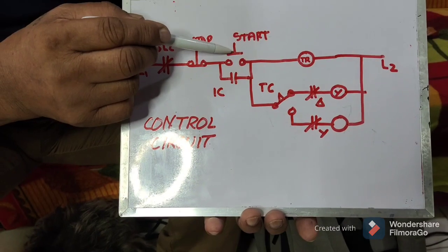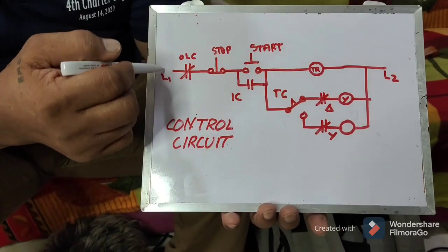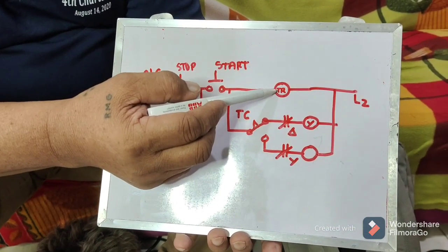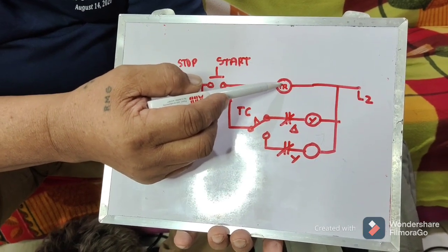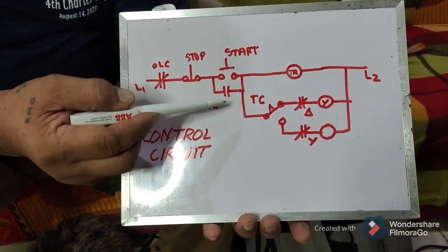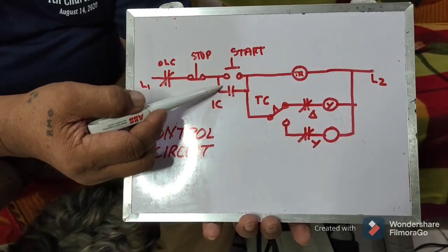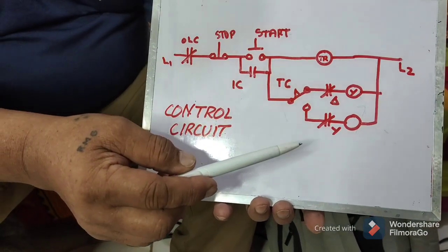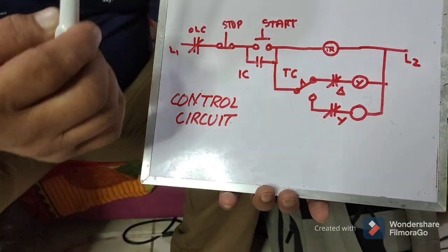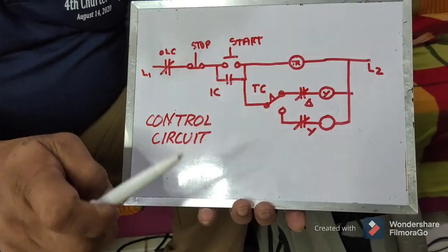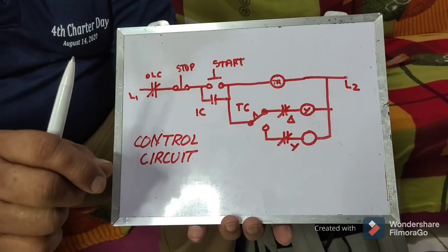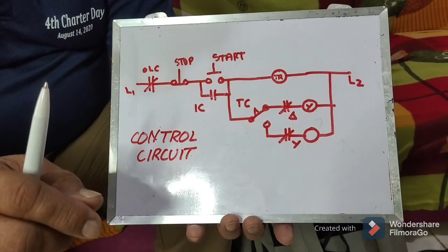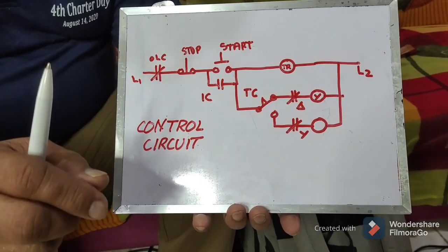But once you energize, or rather press this start button, of course, there will be a continuous flow of current going to your timer. So the holding coil or the magnetic coil of your timer will be energized, closing the instant contact, serving as your maintaining contact, and at the same time, the Y is energized. So in our power circuit, I remember when I pressed the button on, I told you that the Y contactor is the first one that will be energized, short-circuiting the terminals XYZ, or the terminals 4, 5, and 6, that is in the American.